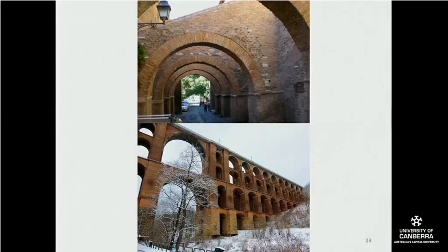And also, older bricks that were fired with less heat are not quite as hard. Even in Australia, the bricks made in the late 19th century were little more than sun-dried bricks, I think you'd say. So when you're looking at 19th century buildings and you poke your finger in a brick, if it crumbles, that's okay. That's just what it does.